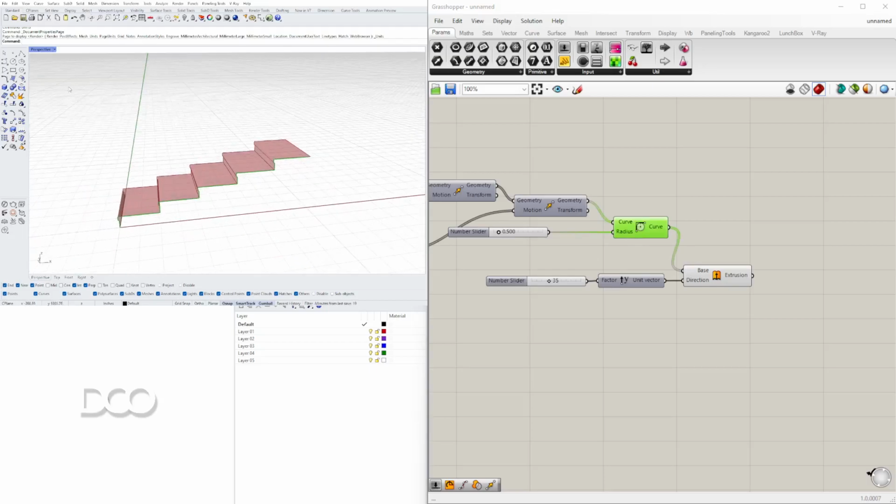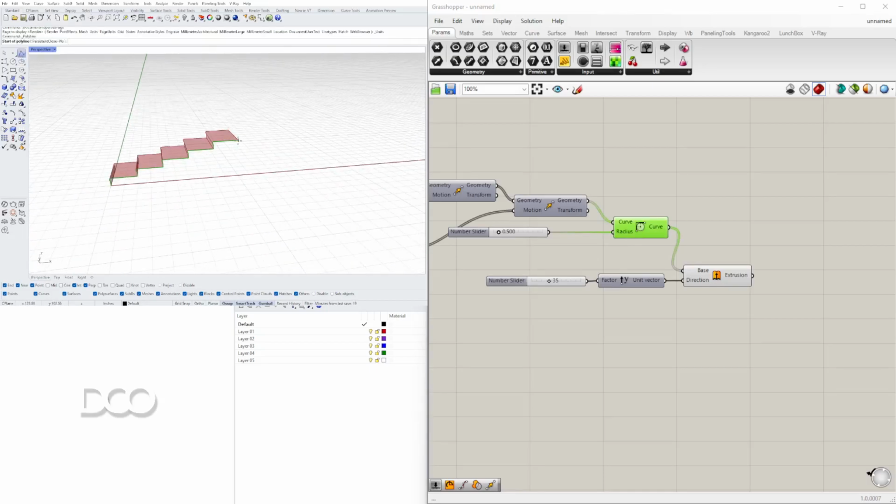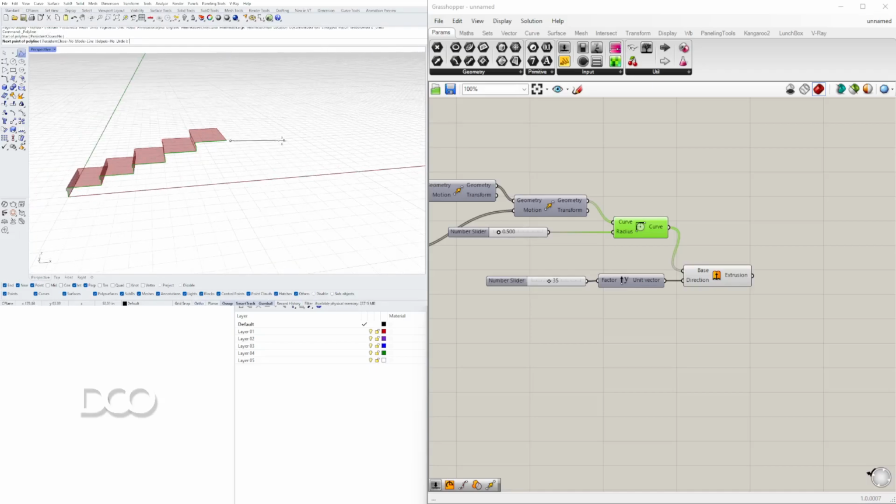Now we have to think about this, that we want another line segment from here to here that creates a landing. Here's the thing. If we are to create a landing and this is 4 feet, well, it would be 4 feet plus 20 inches, if that's whatever the length of this is. So keeping that in mind too, we have to subtract that overall length.